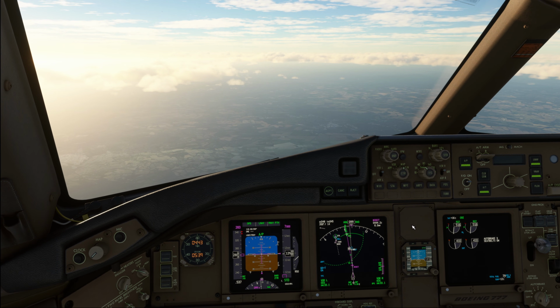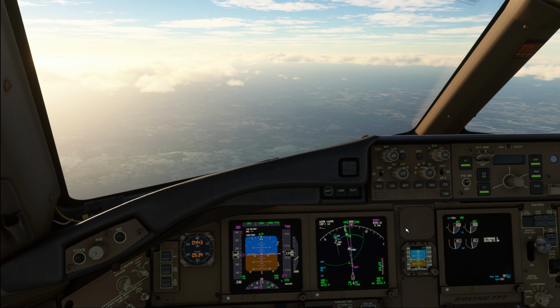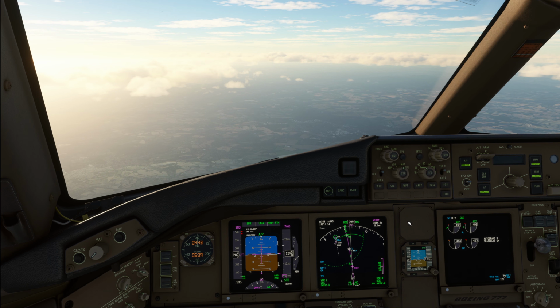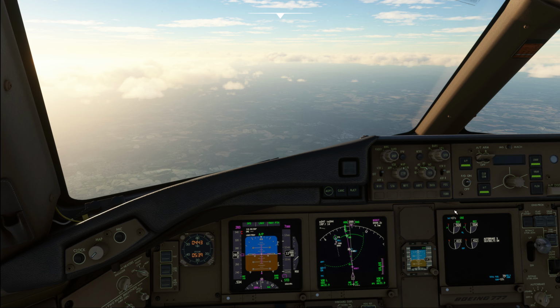A final word here on anti-ice usage. Just like in the climb tutorial, anti-icing in the descent is fully automatic, and you can hear the sirens going off. So the standard Boeing or Airbus pilot does not have to touch it. All you gotta do is check that it comes on if you see the airplane icing up.